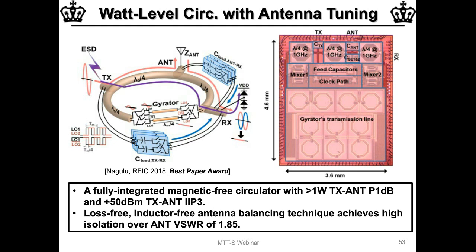and related systems? Yeah, so when you look at the traditional magnetic circulators, if you want to perform an apples-to-apples comparison, one is obviously the power handling is probably still an order of magnitude away. The best we've done is a few watts, while commercial magnetic circulators can easily achieve tens of watts. We're trying to bridge that gap with gallium nitride, and I think initial results show that there's promise there.